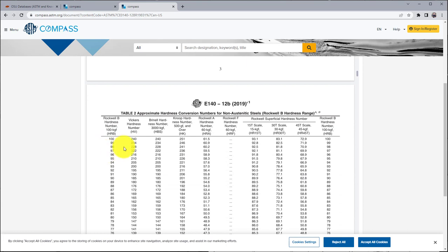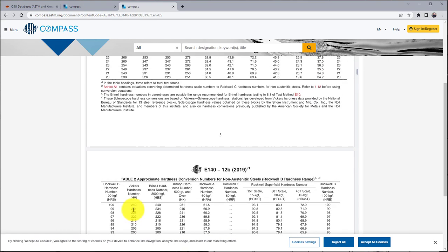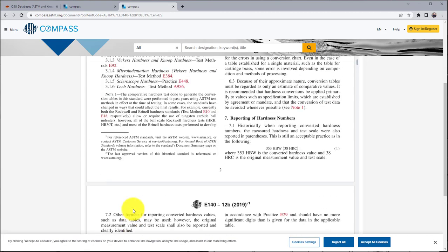Now, we were talking about the Brinell values of 240. If you notice that, we can see a little overlap of the two scales from B to C on that Brinell number as a reference there. And we can see that Rockwell B numbers of 90 are going to be hard on its scale. It's on the very soft side of the C scale. That's why we always start with the C scale and then go to the B scale, and then we go on down to the very soft materials. So that's, in a nutshell, the Rockwell hardness testing on these.